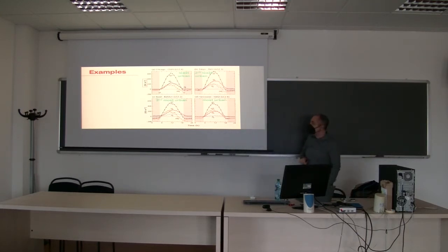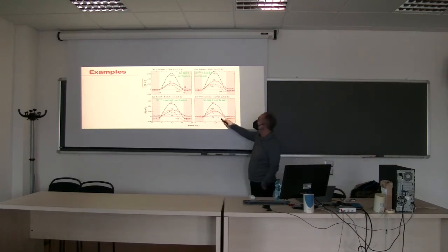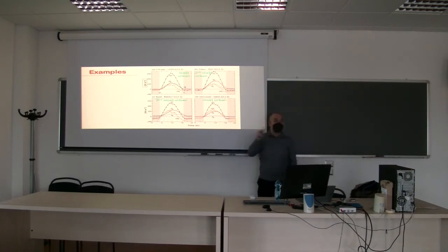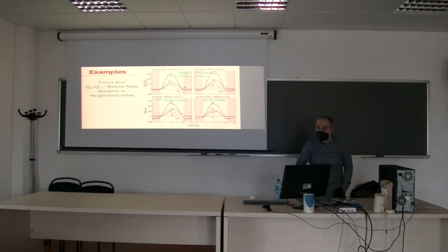You already noticed that the daytime urban heat island is mainly controlled by the lack of vegetation, which makes QH very large. The nighttime heat island is, on the other hand, controlled by the release of stored heat. So the physics of the nighttime and daytime urban heat islands are actually quite different, and that's why you need to think about them and about their mitigation slightly differently.